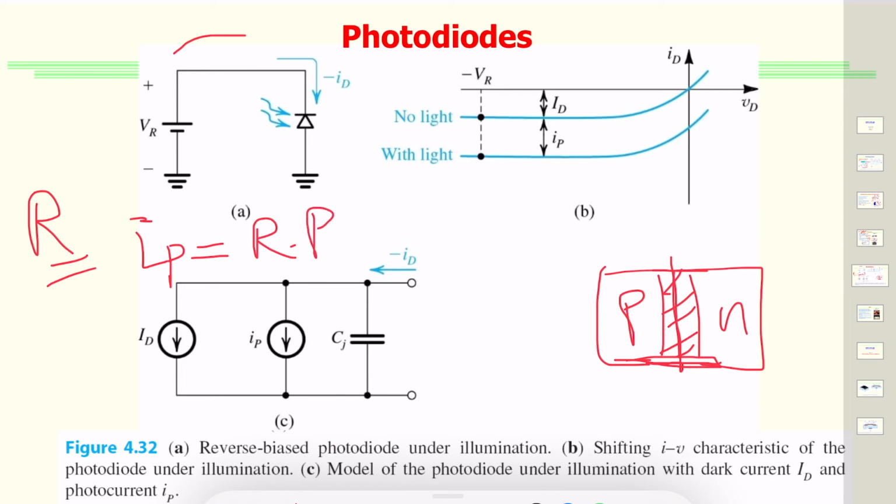The responsivity R of a photodiode is the reverse current produced per watt of incident light power P. Higher responsivity is provided by photodiodes sensitive to longer wavelengths of light, because then each photon carries less energy. Hence, there are more photons per watt of light and more charge carriers caused by them.